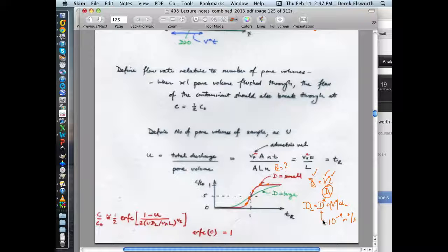And so if this number turned out to be a big number, maybe 2 or 3 or 4 orders of magnitude larger than this, then almost all of it would be due to this magnitude. And you could, of course, if you know the advective velocity, calculate the one remaining component. And so you could calculate what this dispersion coefficient was from that. It turns out, certainly you can do it, and it turns out to be of questionable use because, as we'll find out, the value of this dispersivity, if you like, is typically